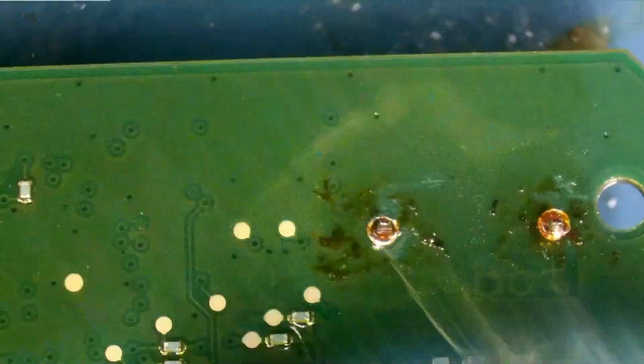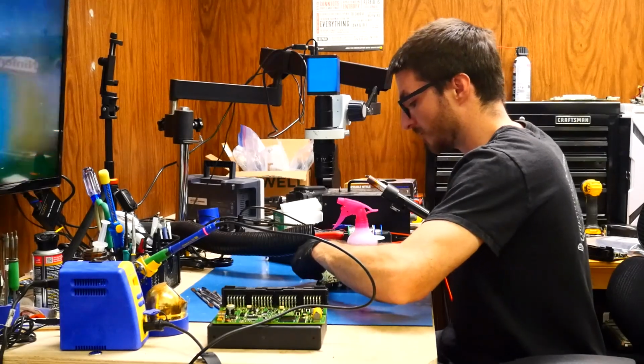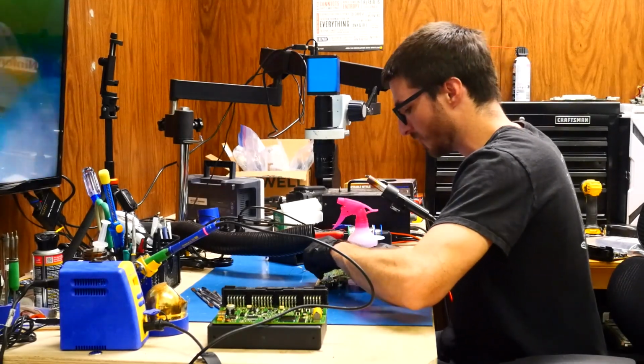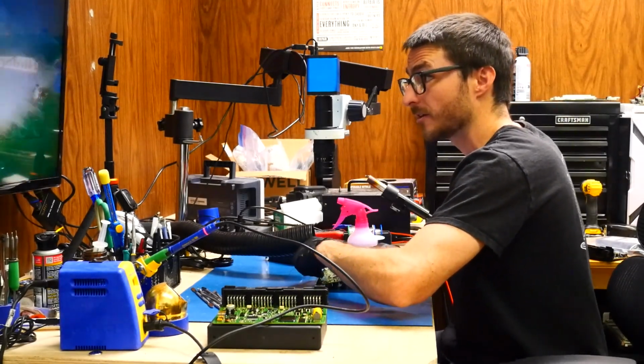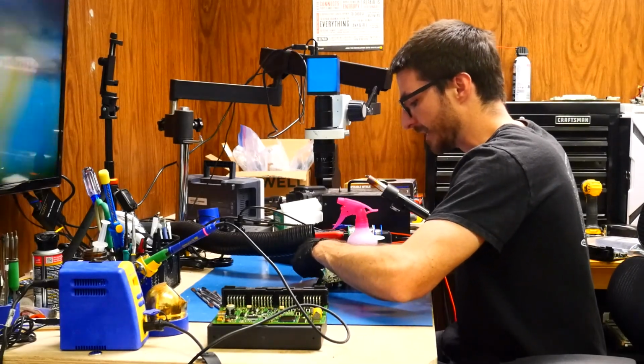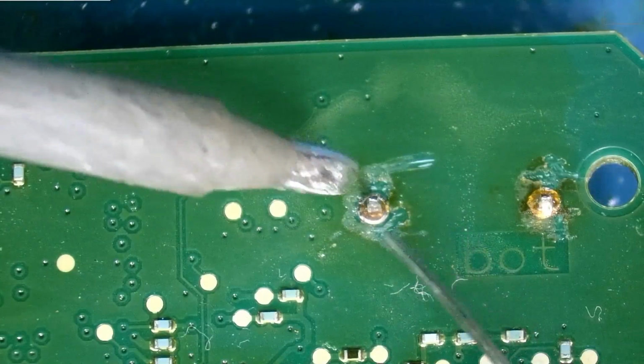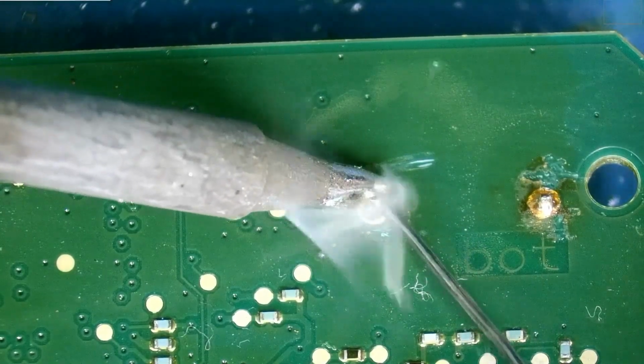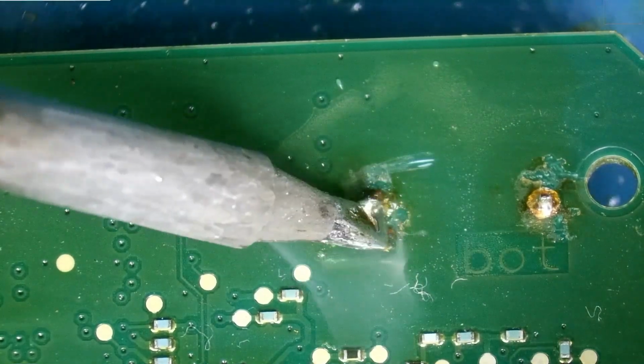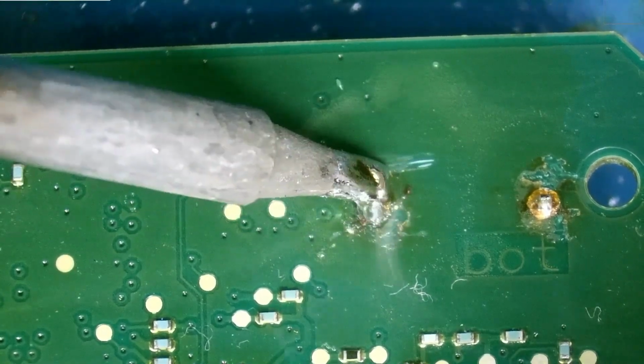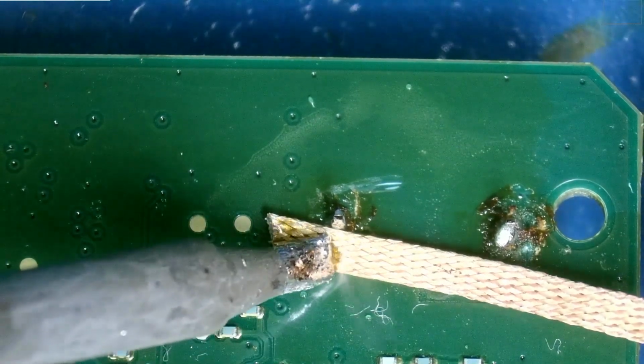Now these two at the bottom I didn't do a very good job, so we're going to go ahead and clean it off a little bit. I'm just using a toothbrush and isopropyl alcohol. And I think part of the problem is I didn't really quite remove all of the conformal coating, so my soldering iron is not making good contact with the solder itself. So to rectify that, I'm gonna just add another round of solder. Yeah, there we go. That looks a lot better. All right, let's try that one more time.